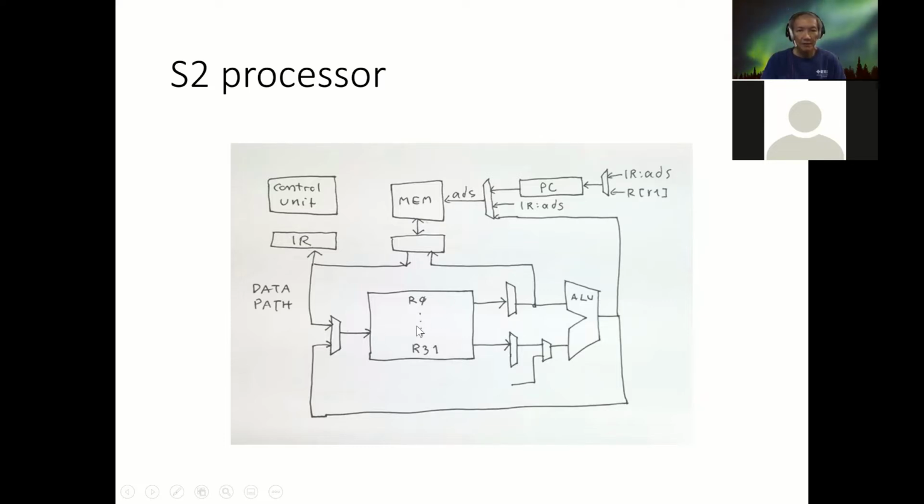That means data from registers goes to the operation and right back to a register, and then load and store instructions just retrieve from the memory into a register, or read from a register, or from the result of the operation, right back to the memory.